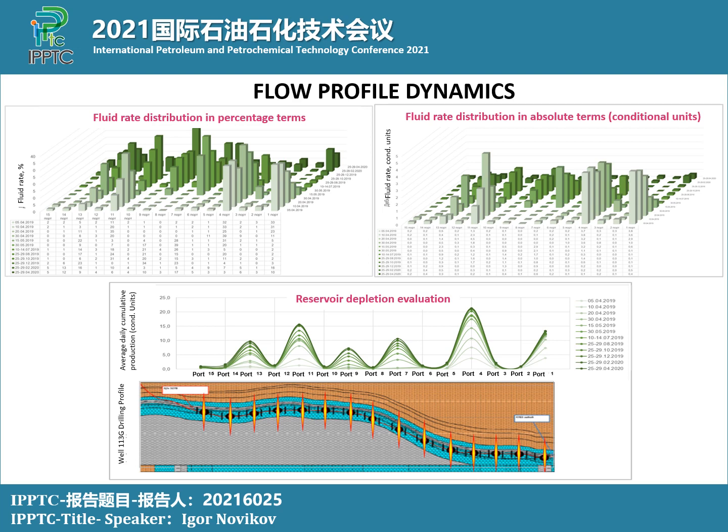And 12 samples were taken during the year, so approximately every month. By cumulative production, we can say that port number 4, number 12, and number 1 give us the most inflow, and some ports give us around 0. So by analyzing this information, we can see how the formation and the particular well work, and we can also predict future processes.